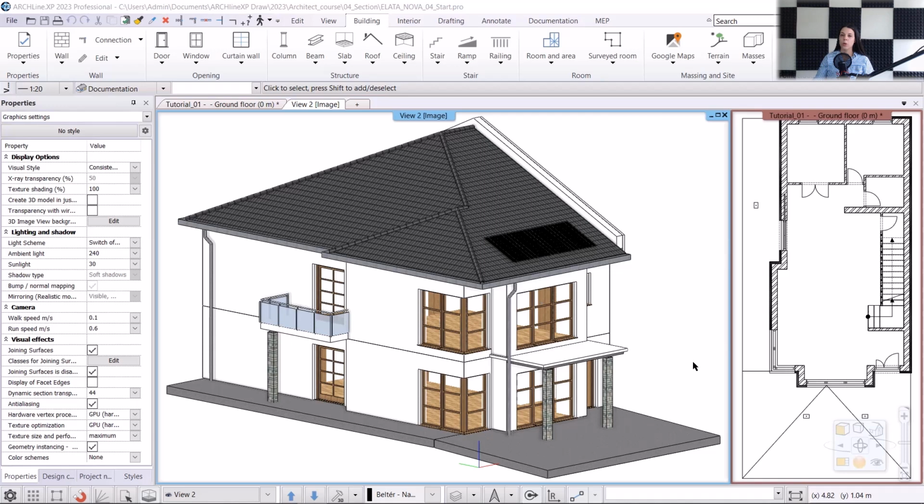The section view allows us to represent elements with or without material hatching, using thin or thick contour lines. When creating the section line, we can set its depth and width. Resizing the cutting region allows us to control what appears in the section view. Once we have created sections, we can manage them in the Project Navigator. We'll see how to do that during the workshop.